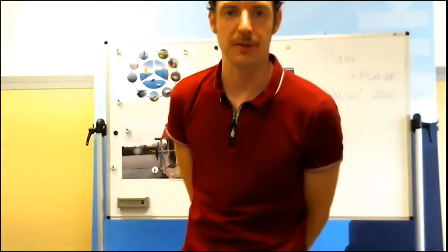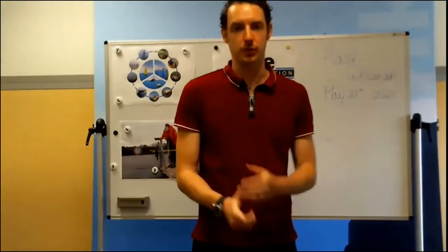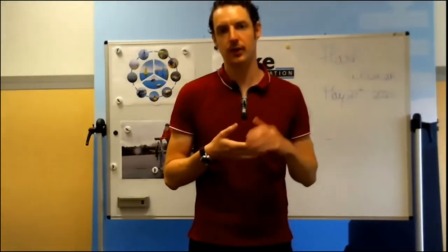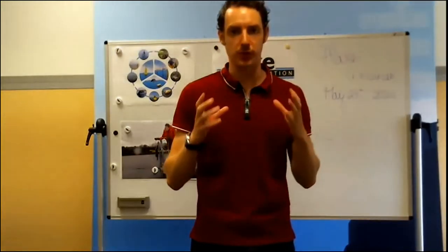I will try to answer them in the good order. What is the frequency for calibration? Also, this depends on many parameters. Typically, the optical-based sensors, turbidity, the fluorimeters, do not require a calibration very often. They just need a point-to-point measurement. We still advise a yearly calibration if you want to be sure.